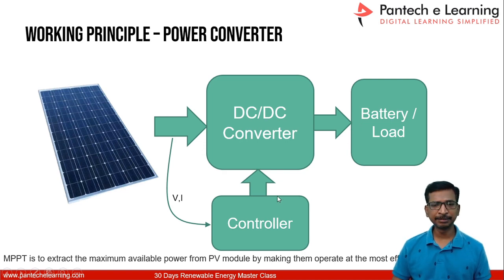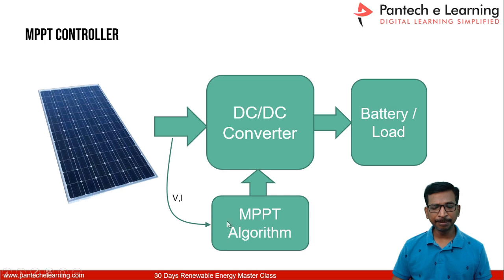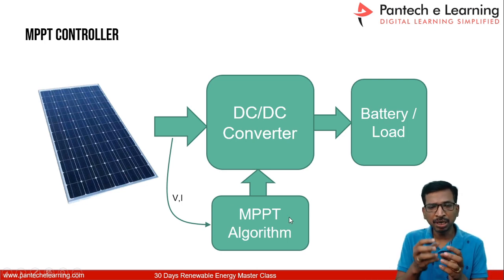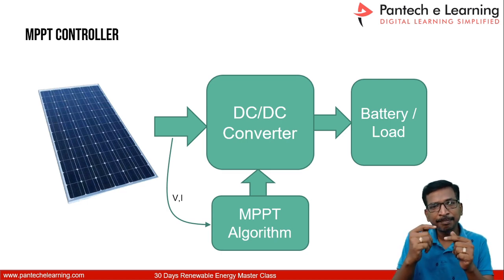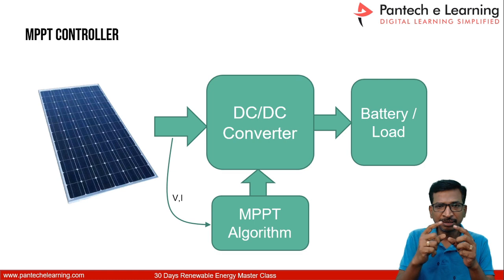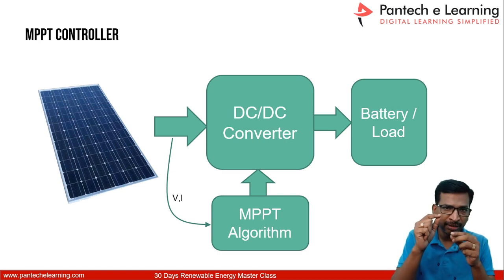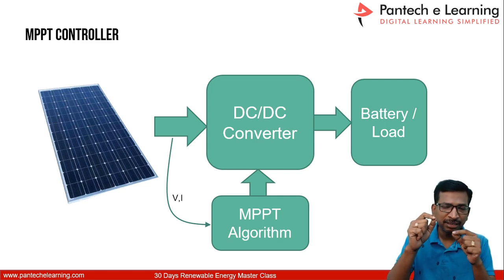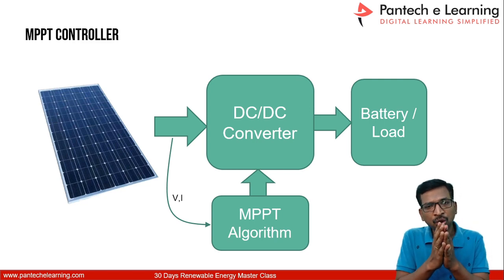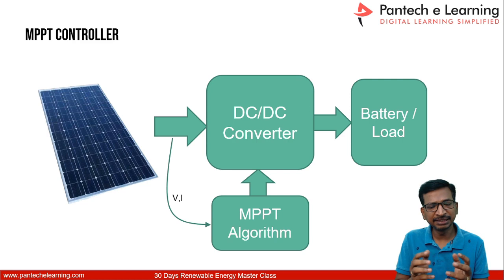On this process, we now have to implement an MPPT controller. This controller should monitor what the maximum power is at maximum voltage. There are two conditions: the power drawn by the converter from the panel is a maximum at maximum voltage. This is the exact condition to operate, or to generate a PWM for the DC to DC converter. Then only can we say it is a maximum power point controller. Or else it's not a maximum power point controller, it's a simple boost converter.